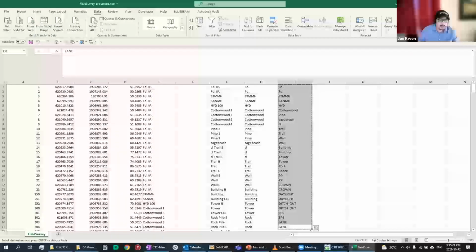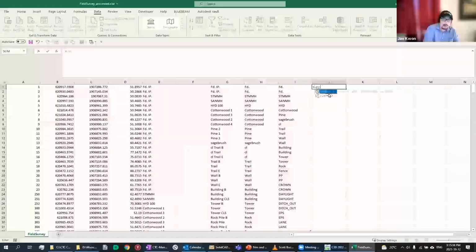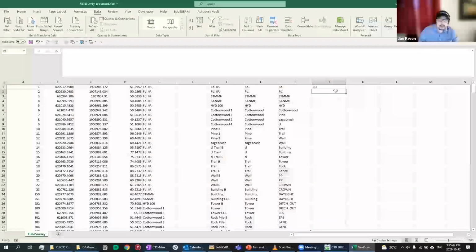And that's something that you can kind of paste into your description keys spreadsheet and then import that in. Right? And of course, description keys are case sensitive, right? So you can clean that up. I'm not sure why that one has a, I'll just call it I1. Right, you can clean that up.